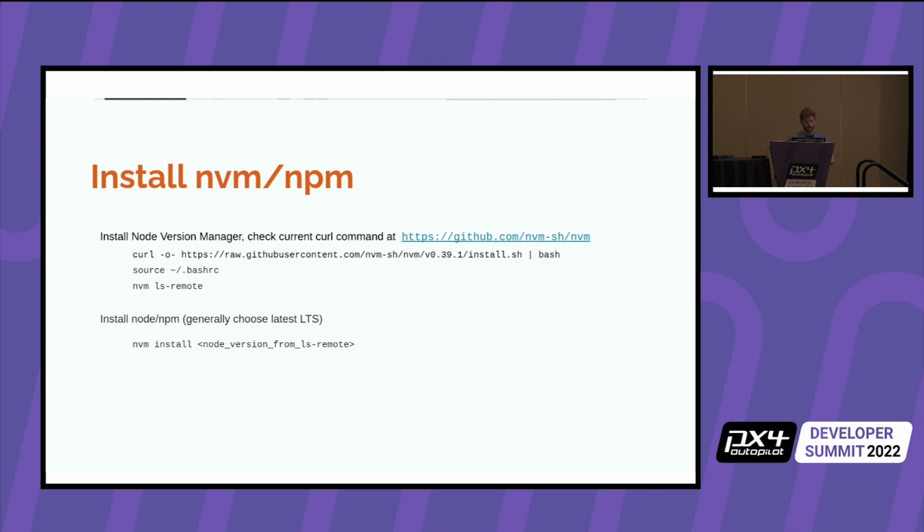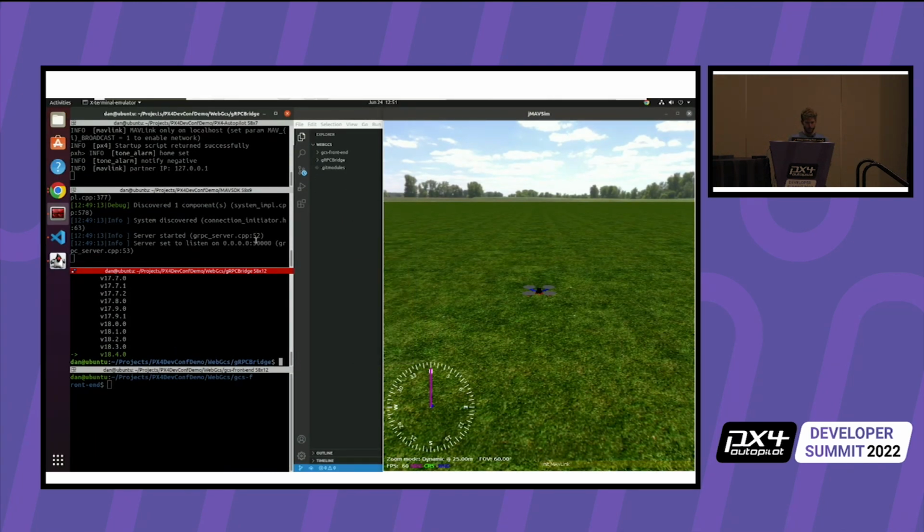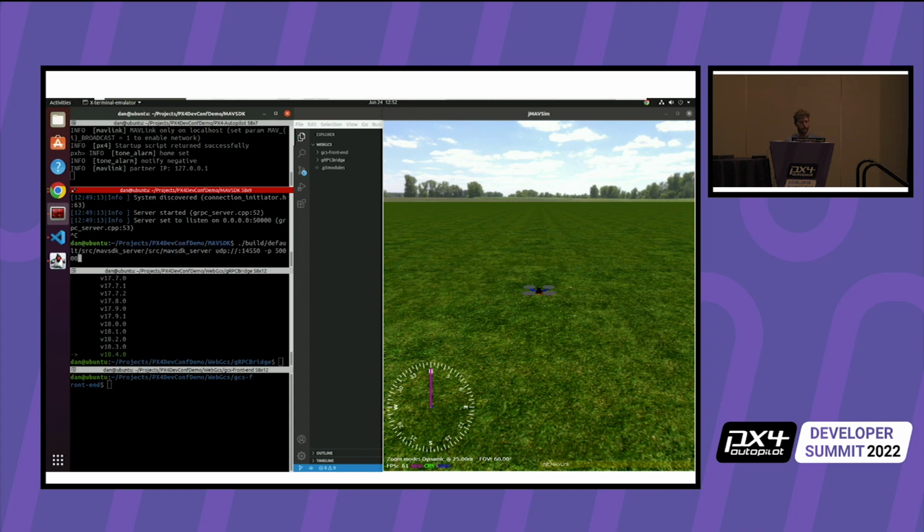Let's see, how am I doing this? You can essentially just set, so right here, instead of just putting UDP 14550, the drone is dialing into this. It's trying to make a connection with this UDP port. So all we need to do is expose it somewhere on the network.